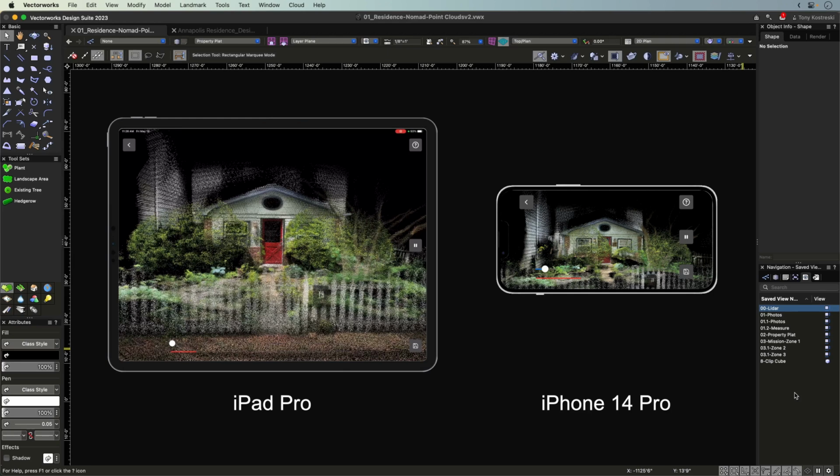And that's simply because the farther you get from the origin, you start seeing this drifting behavior within the point cloud. Also, a completely empty space, like an empty field with just grass, is not going to be as accurate as a space that has more geometry to scan, like walls or different textures on the ground, like grass versus mulch, or plants, fences, and structures like buildings. So if there's more geometry, you're just going to have a much better time and have a much more accurate model. So let's get started with the first site.